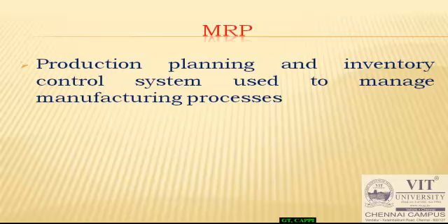Assuming some 1% defect has been produced in that industry. Suppose for 1,000 components, 10 are defective products. Those 10 components will be reduced in your final output. So you have to plan the required material in excess, to manufacture not only the 1,000 components, but to have more than that in your hand. Suppose the demand level suddenly increases, you should be able to make those components also.